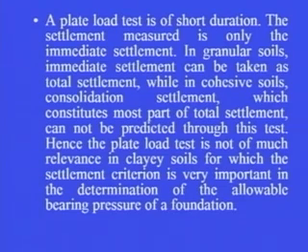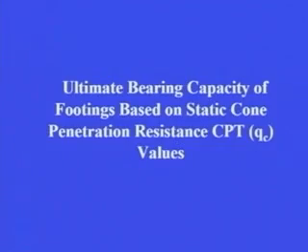In granular soils, immediate settlement can be taken as total settlement, while in cohesive soils, consolidation settlement, which constitutes most part of the total settlement, cannot be predicted through this test. Hence, the plate load test is not of much relevance in clayey soils, for which the settlement criterion is very important in the determination of allowable bearing pressure of a foundation. So, we have to be very cautious when we interpret the plate load test data.